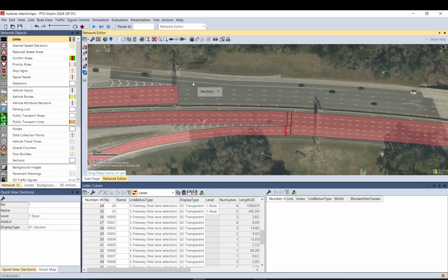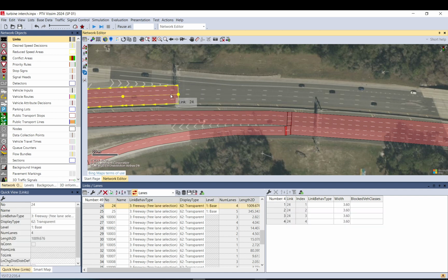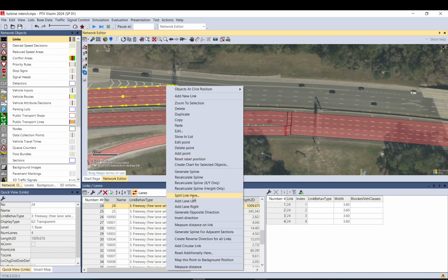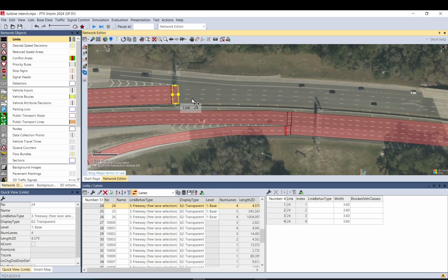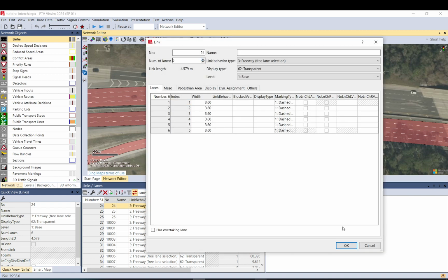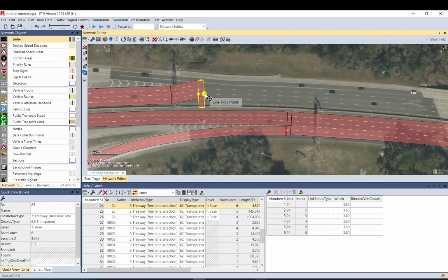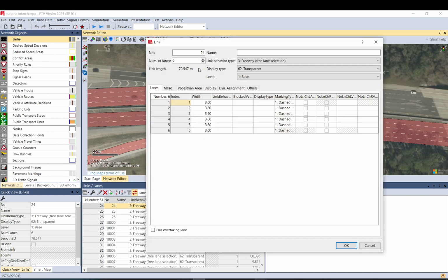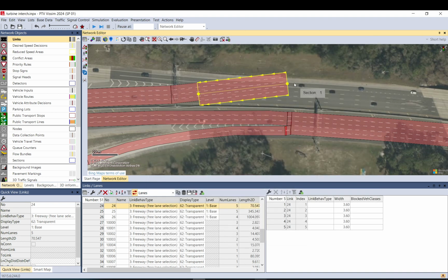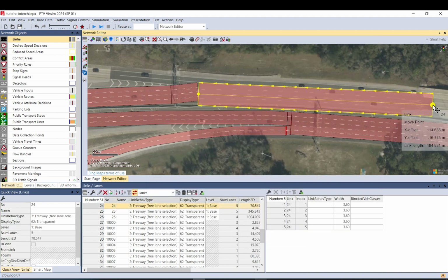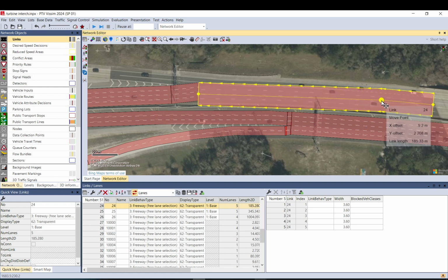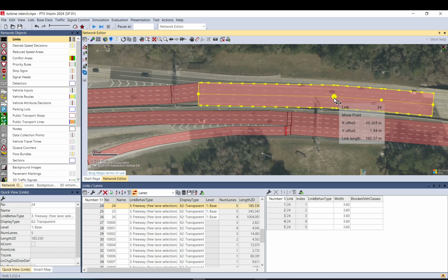So I'm going to show you here in this one what is the other way to model it in case you have issues. Issues, I mean too many lane choices and not realistic queuing. So what you can do in that case, you just basically create a 6-lane road here. Is it 6? It's 5. Sorry. So you basically create one like that.